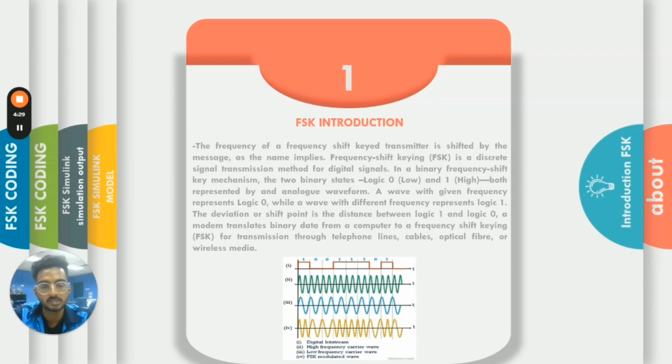As we know, digital signal is always 0 or 1. So in a binary FSK, the logic 0 is low and logic 1 is high, both represented as an analog waveform. So a wave with a given frequency represents logic 0, while a wave with a different frequency represents logic 1. The deviation or shift point is the distance between logic 1 and logic 0. A modem translates binary data from a computer to a frequency shift key FSK for transmission through telephone line, cable, optical fiber, or wireless media.